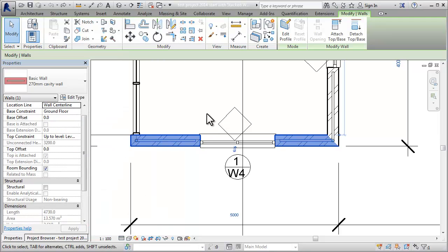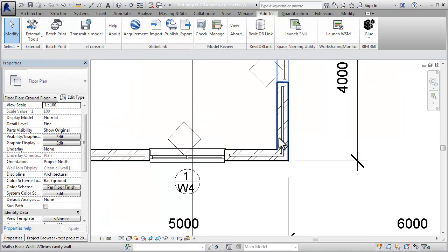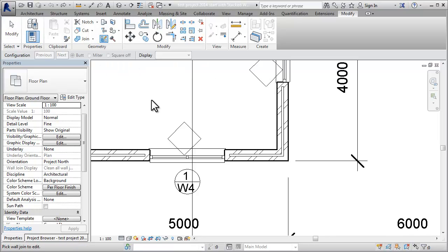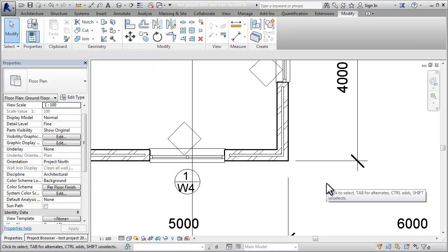Right, that done, you can also look at how these two connect. If you've got two connecting walls, by default it doesn't connect via the mitre area. It usually connects butt joint, and it's a good idea to just set it to mitre, as it then gives you more accurate external lengths. Obviously these external lengths are used for the mechanical part of the fenestrations if required.